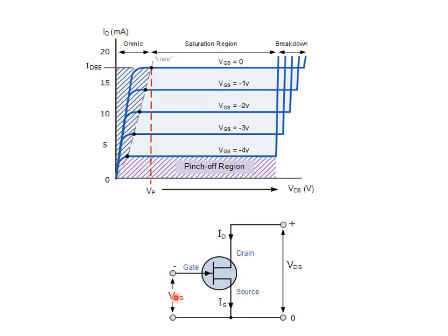If we have VGS equals 0, that's when the maximum current will flow. When we start to increase this in minus, so after 0 maybe we'll have -1, then the current will start to decrease, until we reach a voltage that will cause this current to completely stop, so 0 current. So this will be like a switch off.